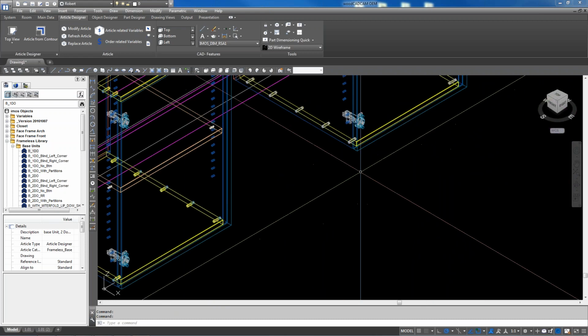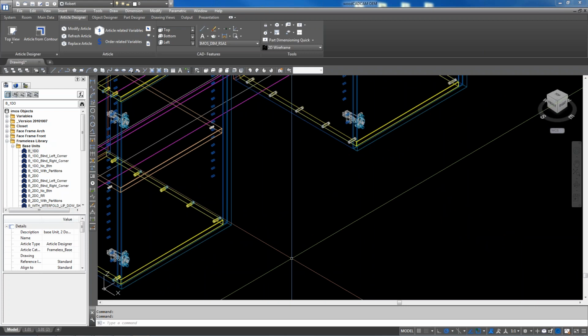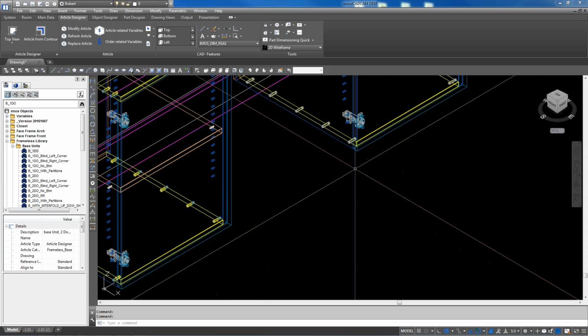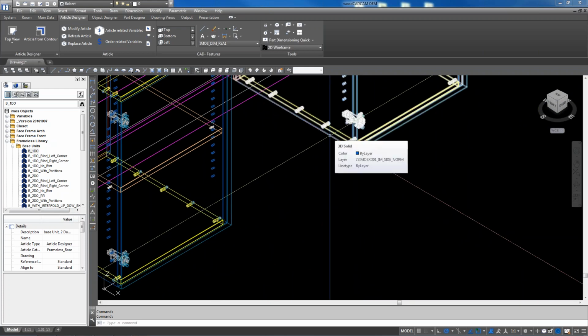So we'll go down here between these two guys, over the toe kick. Set the back a little ways to match up with the toe kicks. That's correct. Usually we can set it back just like other cabinets, about 3 inches.